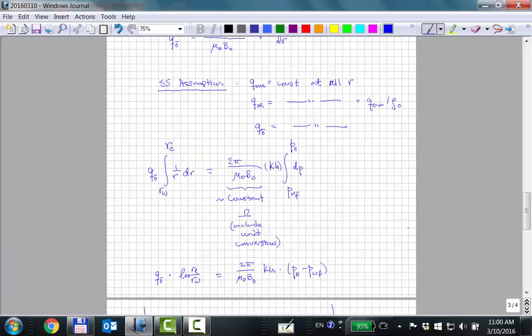Okay? And if what goes in goes out, it says that basically we're not accumulating anything in between. If you take the derivative of that with respect to time, that's the rate. The rate has to be the same everywhere where it's flowing. And here it's flowing at the external boundary. Why is it flowing there? Because the pressure is constant. The only way to keep the pressure constant is if something's flowing in there.